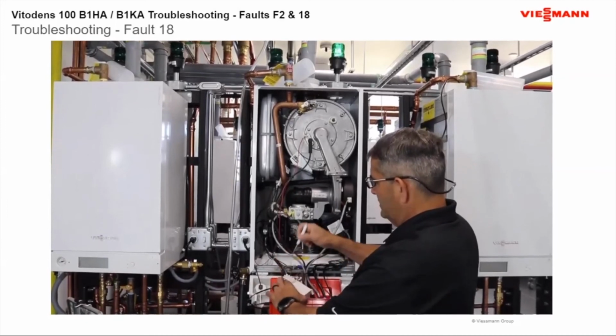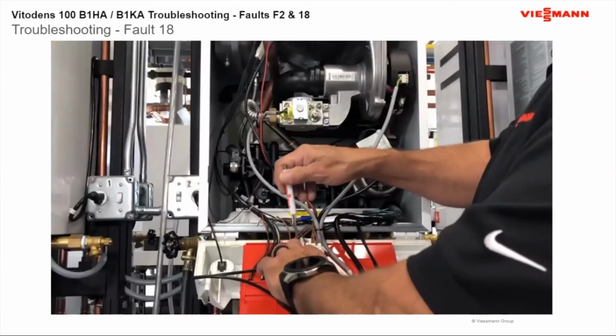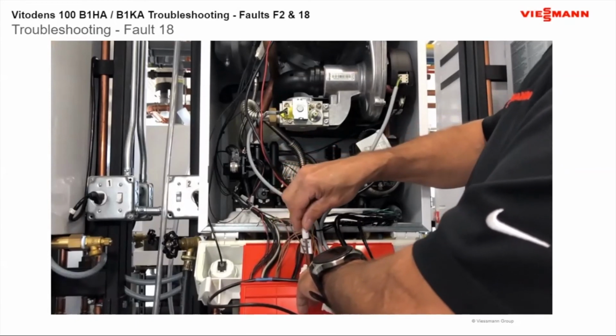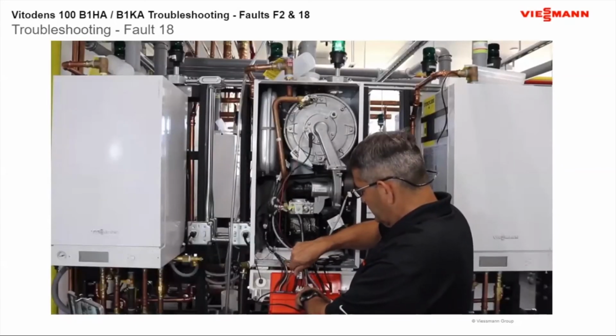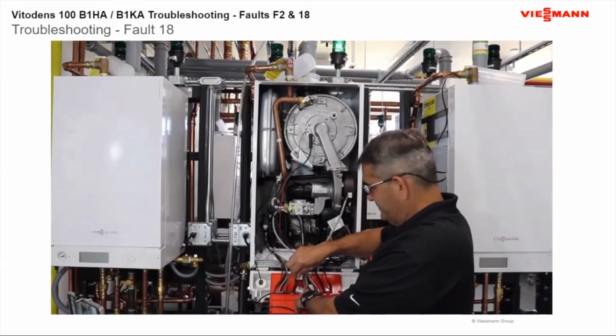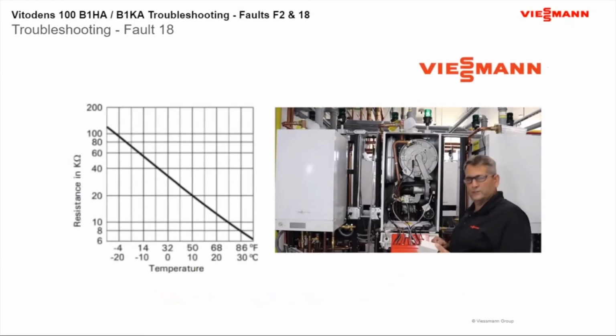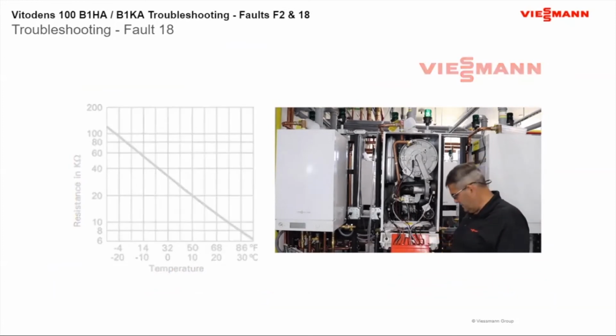So we're going to take our wires off 3 and 4. And then inside our chart or in our pro resources, it will ask you if you want to see the manual itself. So we can go into our manual or on our pro resources and see the manual there as well. We're going to look up on our chart for a fault for our outdoor sensor. There's actually a chart to test our outdoor sensors with ohms.